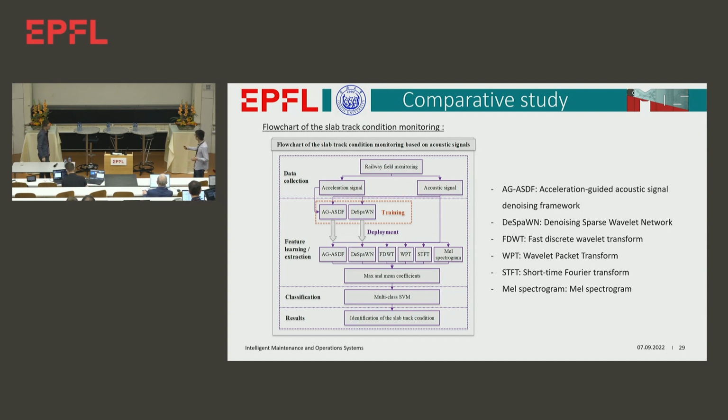And we take the maximum and the mean coefficients of the time-frequency or wavelet coefficients from each filtered frequency band of signals and features. And based on a multi-class support vector machine on these features, we can evaluate the classification performance of using different feature learning or extraction methods.